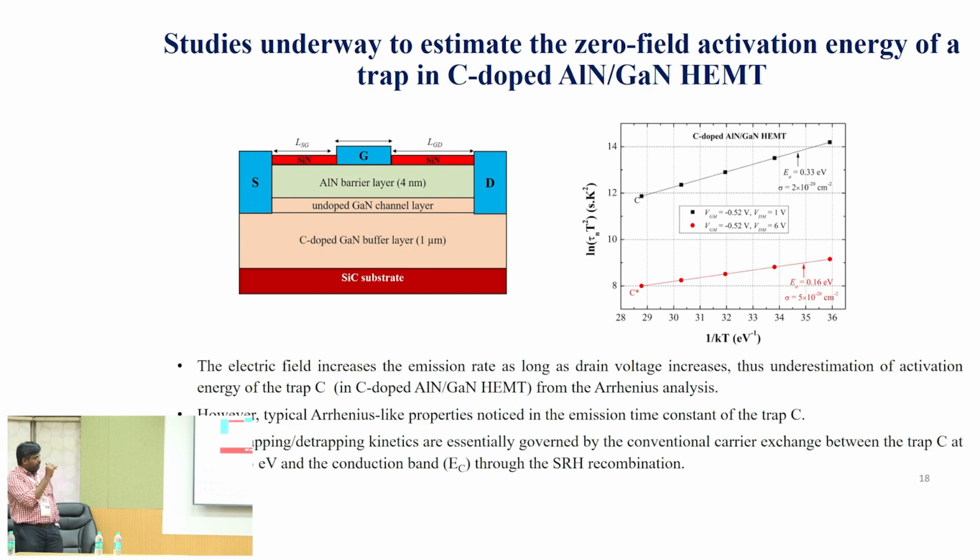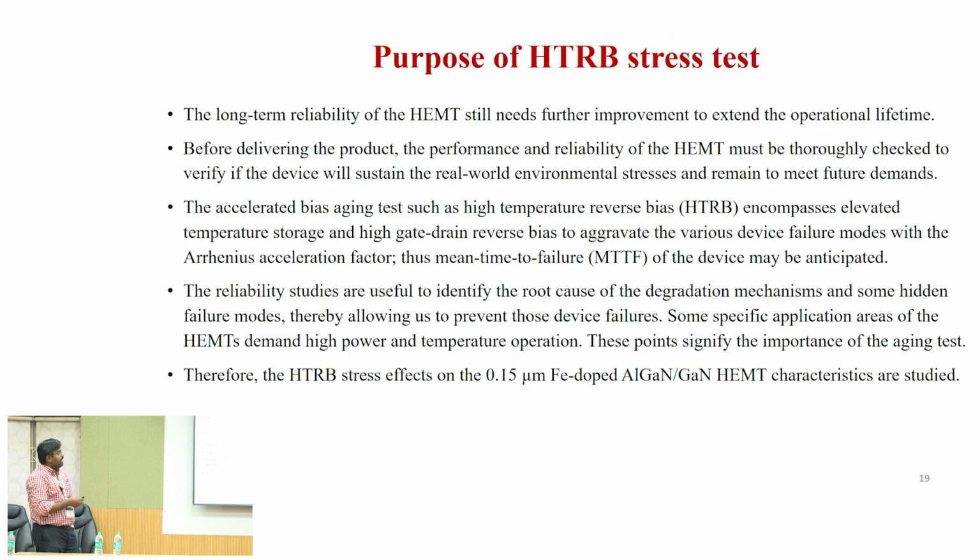So these traps are behaving following the emission rate as per the SRH recombination theory. Okay. But the studies are underway to calculate the zero field activation energy for these devices. Then the second section is related with the high temperature reverse bias stress test effect on the HEMTs.